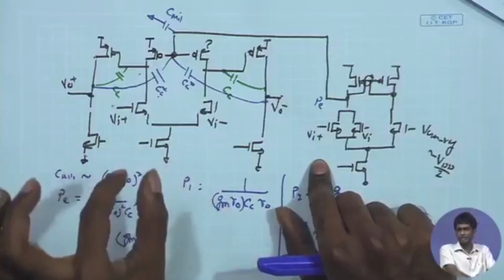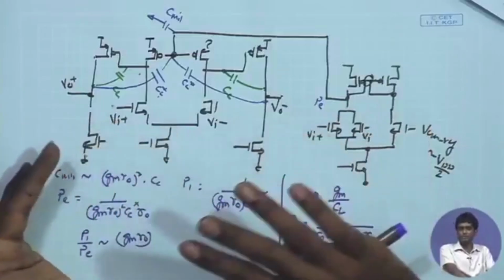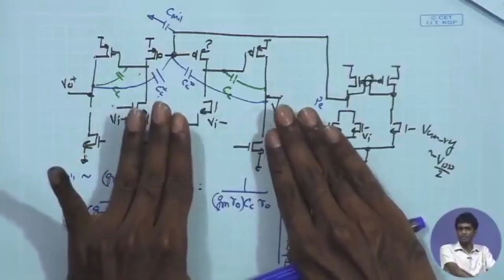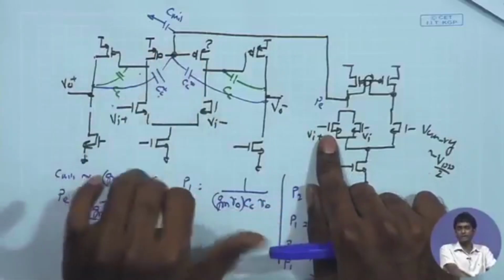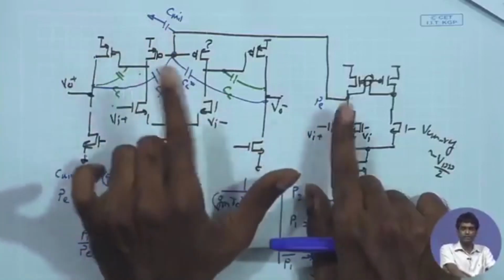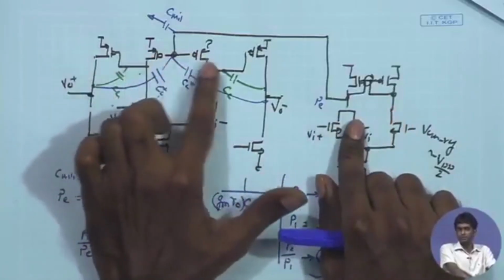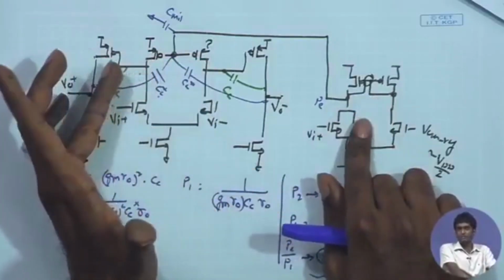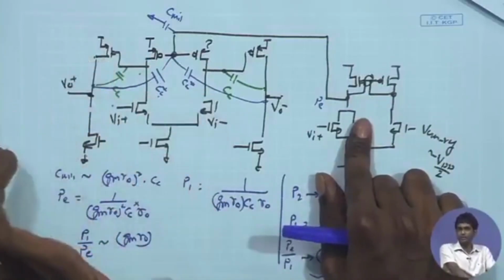So, ultimately you are using long channel length, right. So, MOSFETs in analog design you will be using long channel length, like 1 micrometer. It is not really that if you are using 180 nanometer technology, the devices you will be using are at minimum channel length. You are using pretty large channel lengths. For example, for noise we consider this to be having much larger channel length, so that you can have the input referred noise small, or the 1/f noise corner can be pushed towards lower frequency. So, that forces us to use long channel lengths for this one, maybe even 10 micrometer. That is pretty common. Even for 180 nanometer devices, you may be using a channel length for these guys which is probably 10 micrometer, 20 micrometer. That is not uncommon. Likewise, for the input devices, you are probably using at least a few micrometers, so that the gain is sufficient.